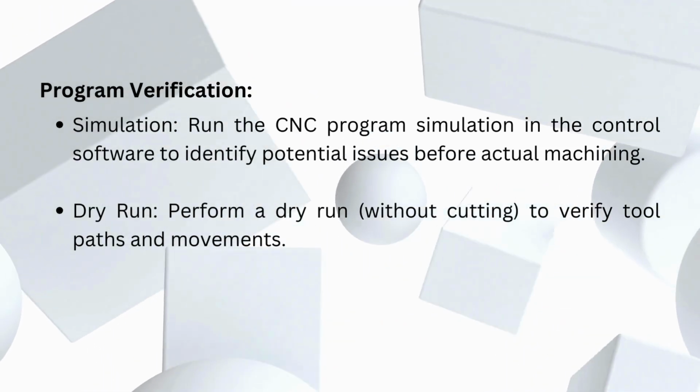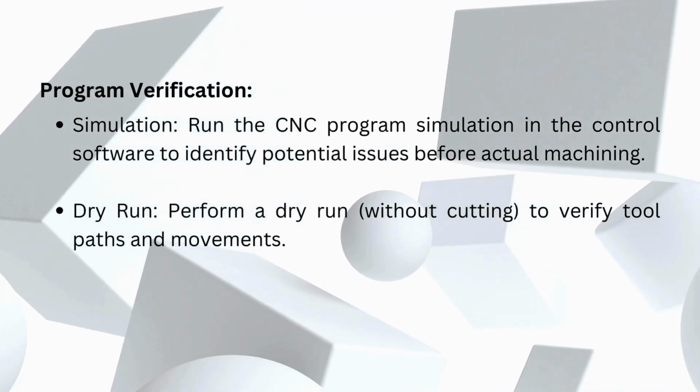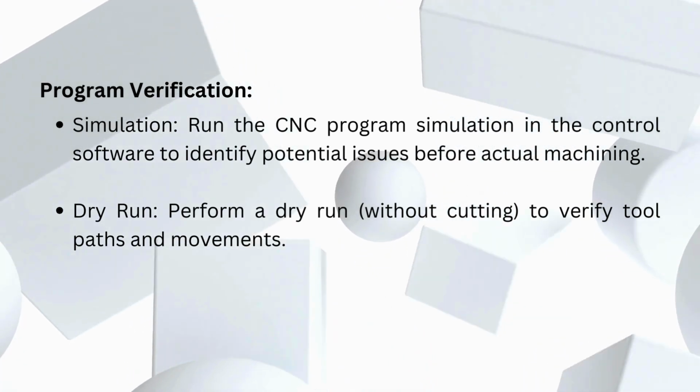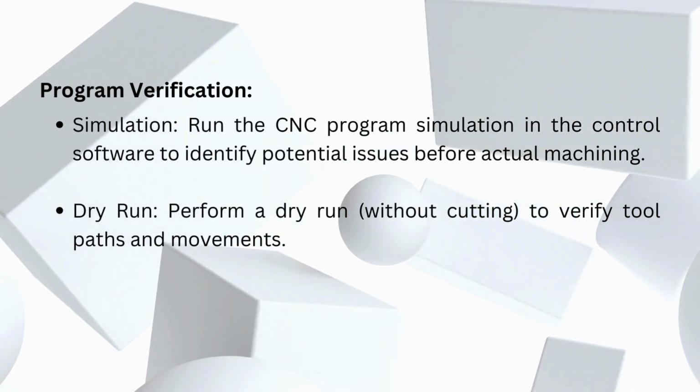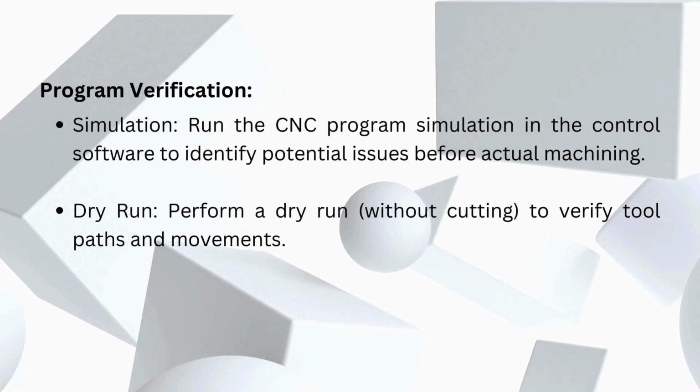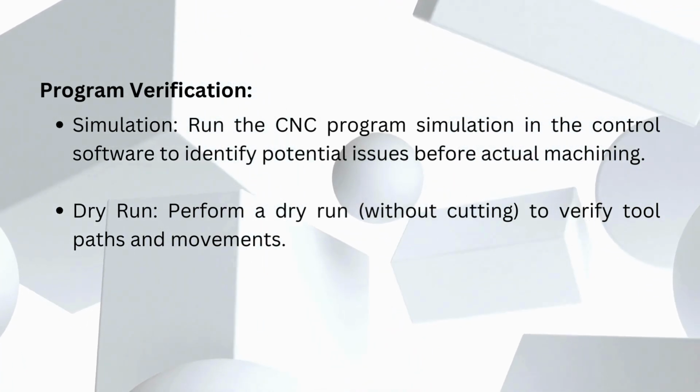Program verification. Simulation. Run the CNC program simulation in the control software to identify potential issues before actual machining. Dry run. Perform a dry run without cutting to verify tool paths and movements.